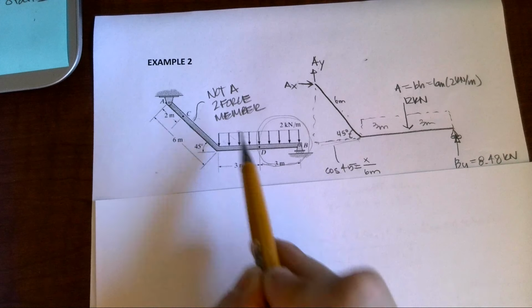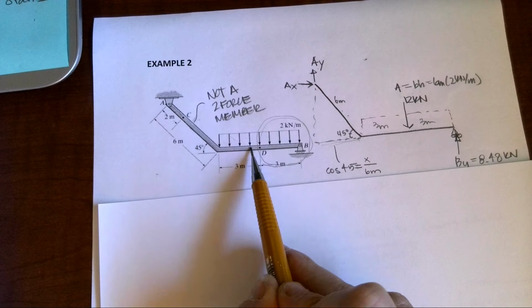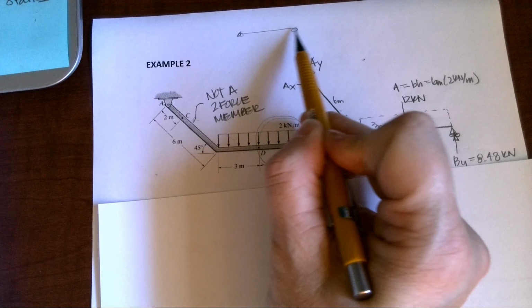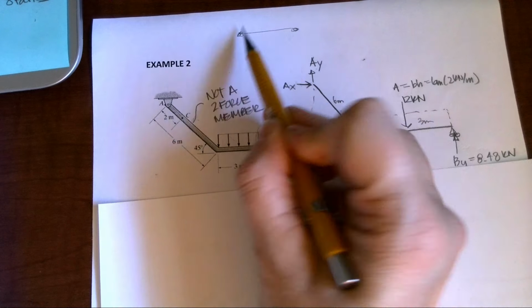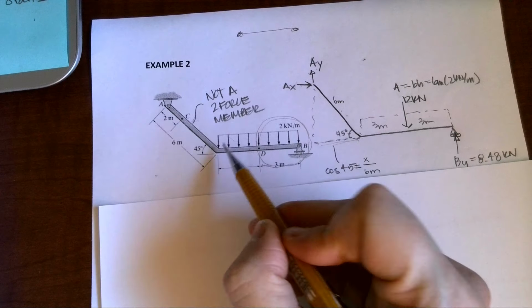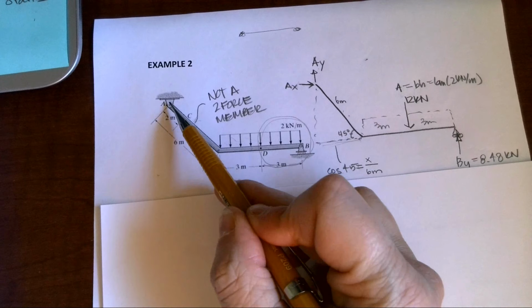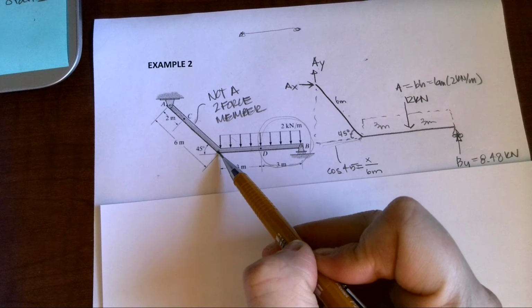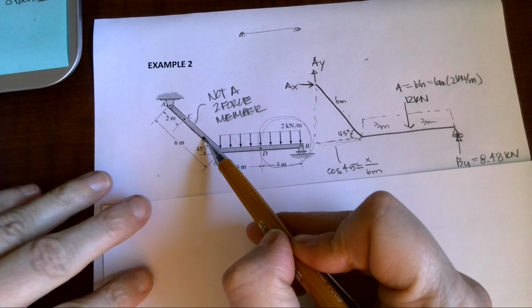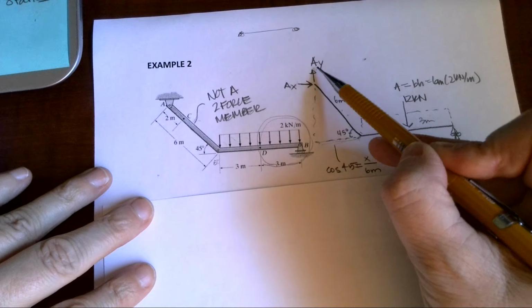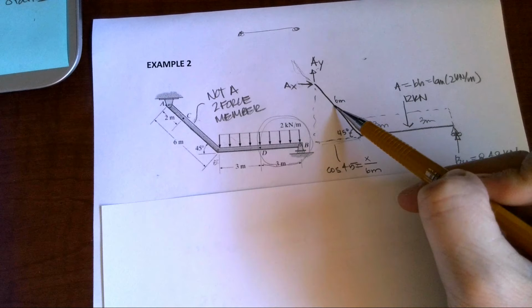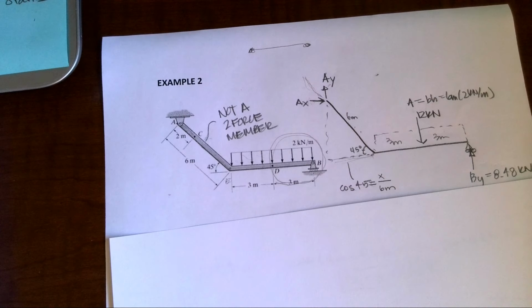So this actually has a load on it, not two-force. Remember, a two-force member is something that's pinned on both ends. If B was actually a pinned reaction and I had a pin at A, let's call that E, and E to B, then yes, we could call this a two-force member, and we would know that the X and Y components would have to follow the same direction as that two-force member in terms of geometry, but that's not what we have.